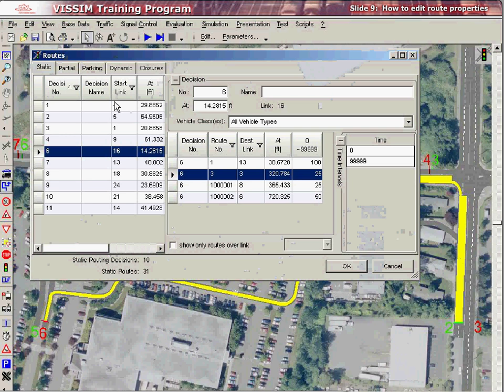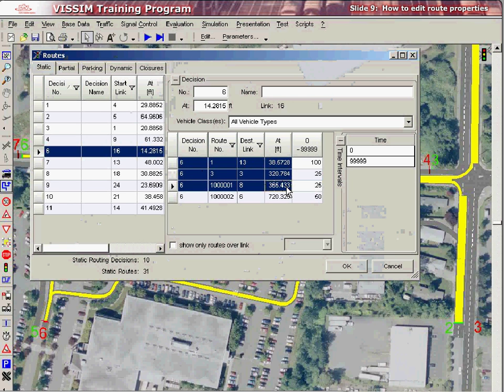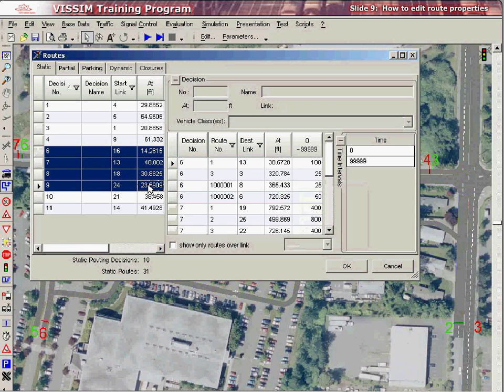In both the Routing Decision window and the Route window, you can select one or multiple lines and then copy the information to the clipboard to be pasted into Excel or other programs by simply left-clicking and selecting Copy. If you select only from one column, you also have the ability to paste, so you can very easily edit multiple routes' volumes at the same time, reverting to 0 or 1 in preparation for converting a copy of an AM scenario file to a PM scenario as one example, or simply copying the volumes from Excel directly into vSIM if you have this information in that format.